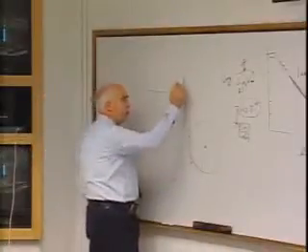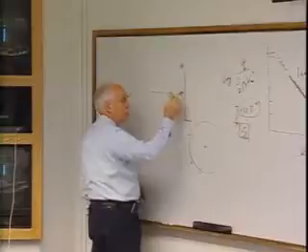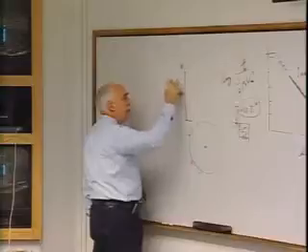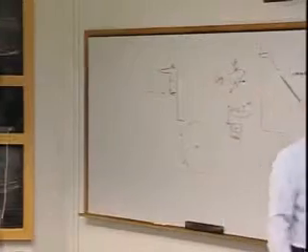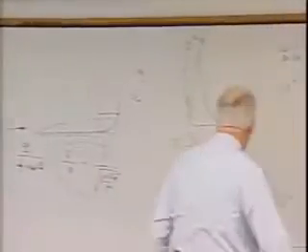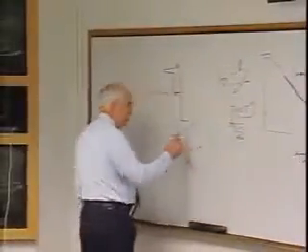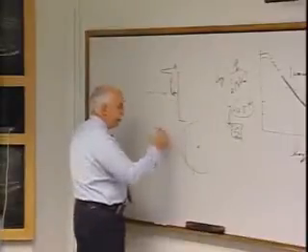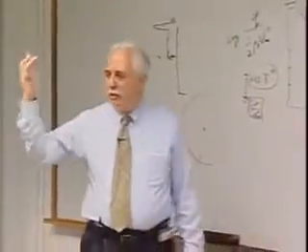One other problem, if I use just a section of a flat plate, if I look at the heating distribution, if I plot the heat transfer in this direction, from ground test and not from flight, you have some level of heating, but then when you get to the corner, it really goes up because of the pressure gradient, the same thing that we experienced on Apollo in terms of the ablator. So you want to give it some curvature, not only from the standpoint of stability, but also from the standpoint of the heating distribution. And indeed, if you look at the Apollo at zero angle of attack, it has pretty much a uniform heating distribution.